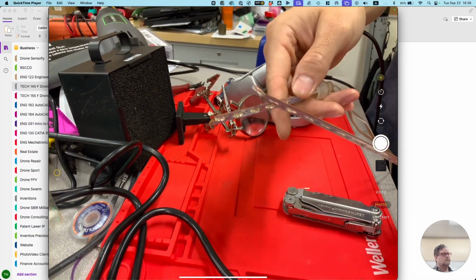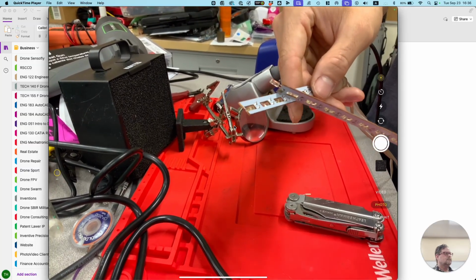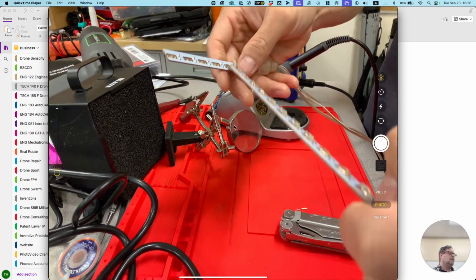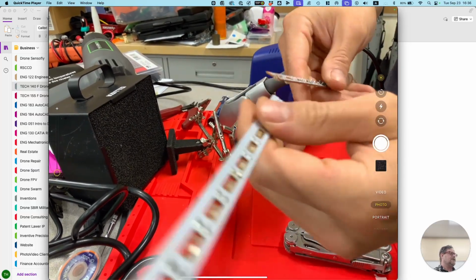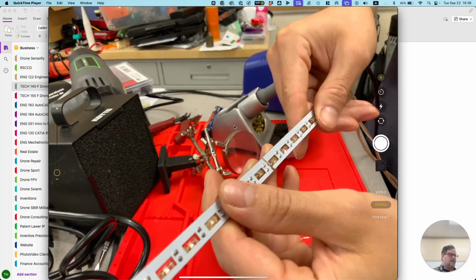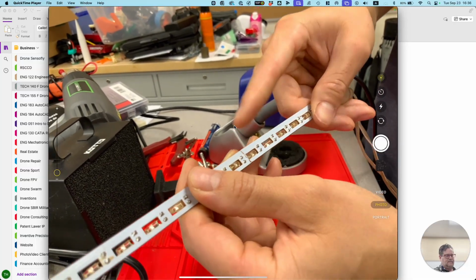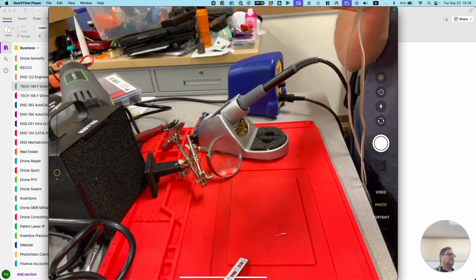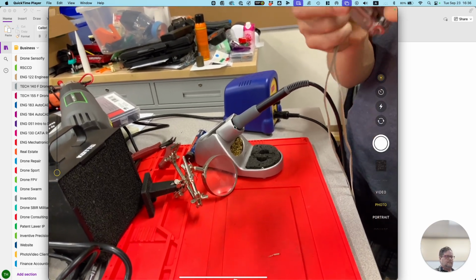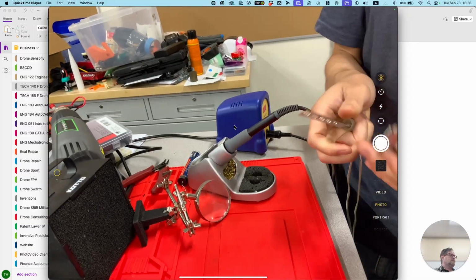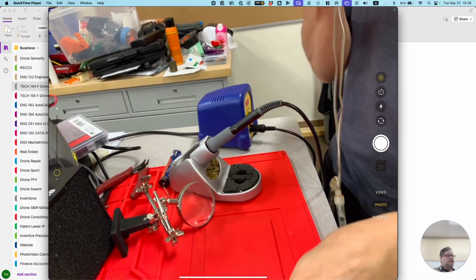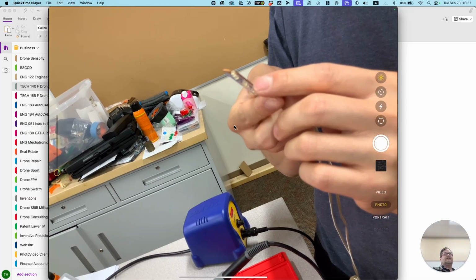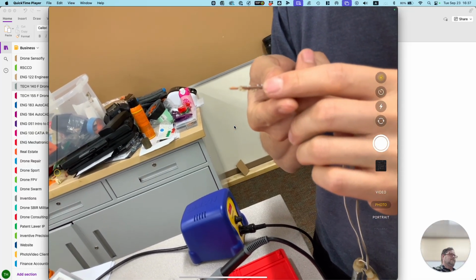Inside, there's multiple layers on this thing. Inside, there is a copper connection. Now, these are covered right now. I was going to say it looks like a single surface with a solder mask on it. Yeah, so these are covered right now, so you can't see the copper connection. So what I need to do is scrape away the coating, and then I can access the copper inside. Having worked in circuit boards, that's solder mask. Solder mask, okay. And then you'll just solder the copper.